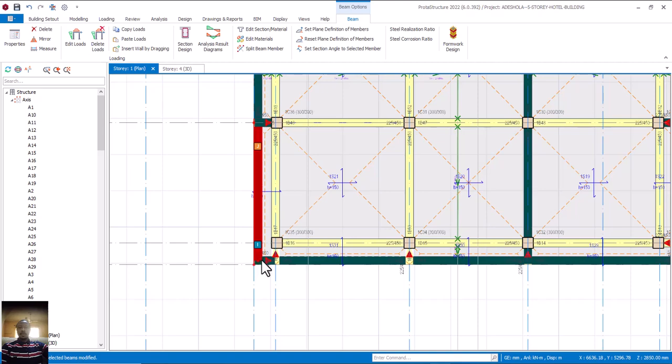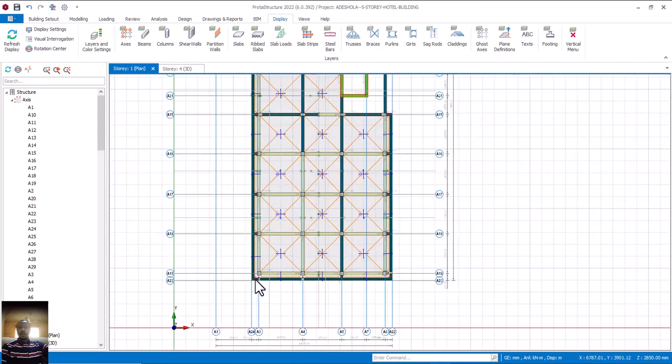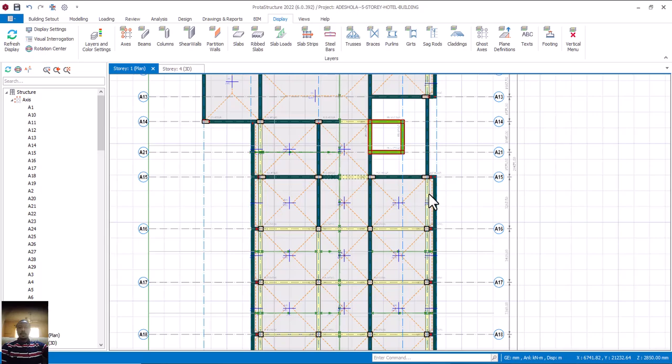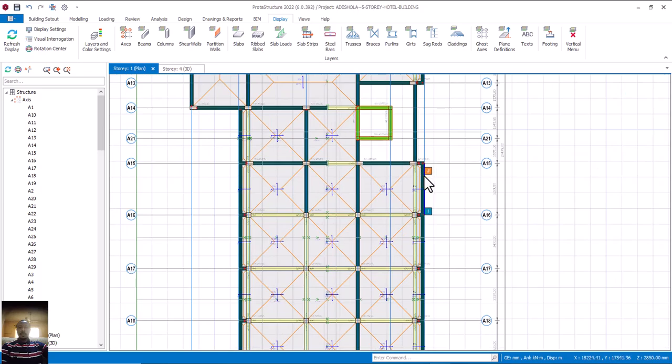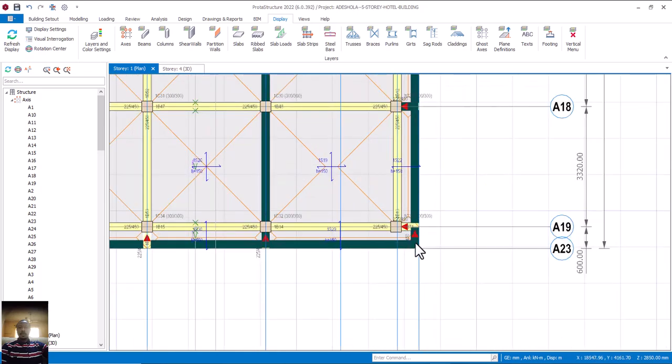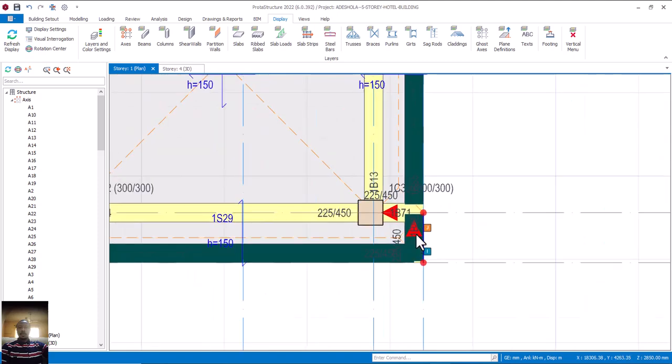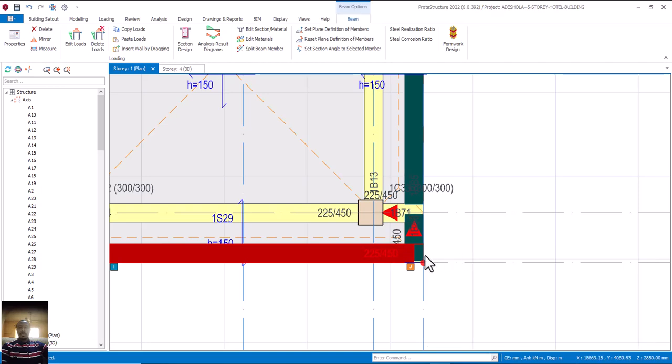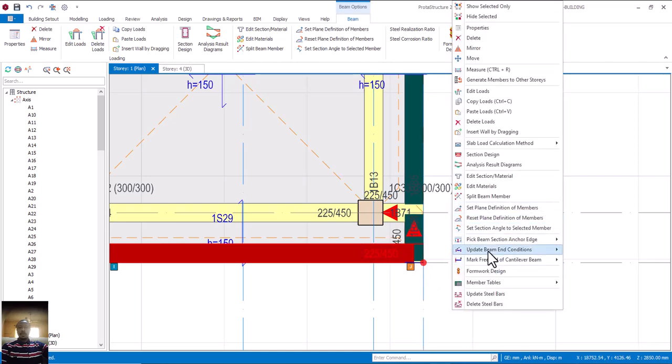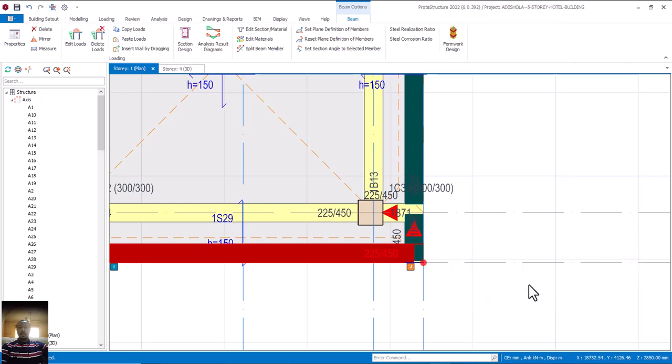Let's also continue this other side too. Okay, it's done. This place is done. Now this one also is done. What about the downside? Okay, this one we are not going to hinge. Why? Because on this other side is a cantilever, isn't it? So it's this one that we are going to hinge on this other side, which is our J. Is that okay? That's our J. Okay, I'll come to J and then click on apply.